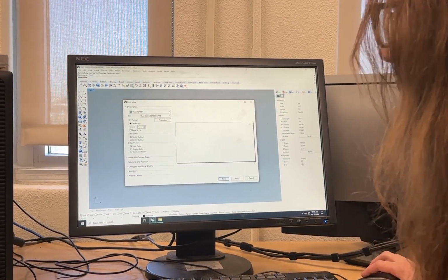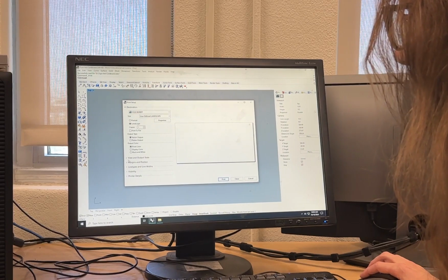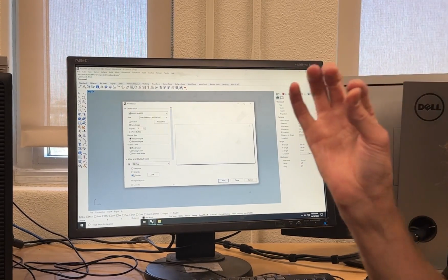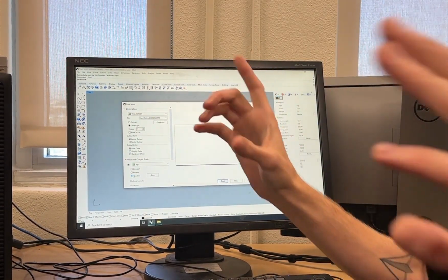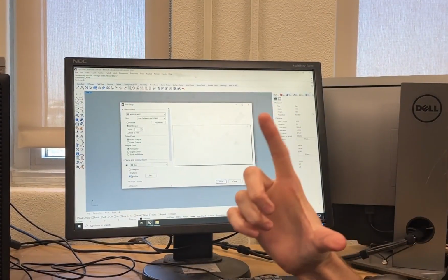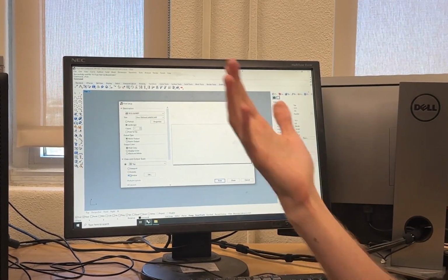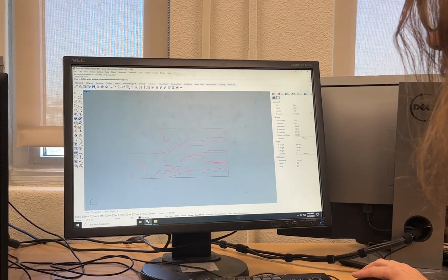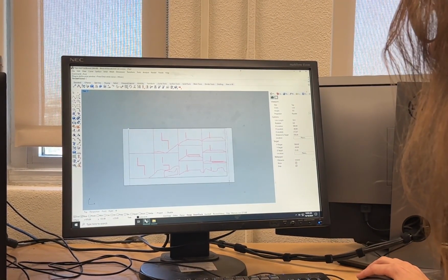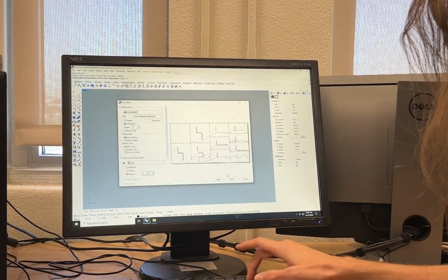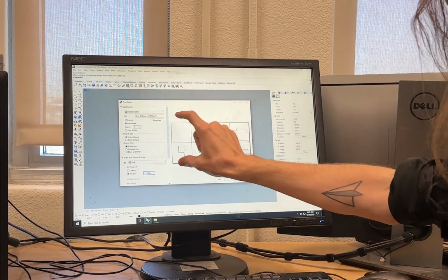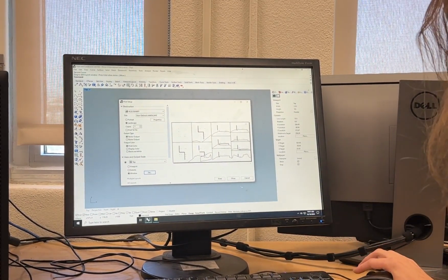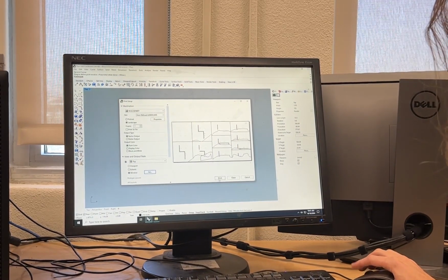Lastly, we need to go to the view and output scale, and we need to select window, right? Because we made a window for ourselves, and now we need to set that window to this window. And since we set it to scale 12 by 24, we'll have no issue, right? So we'll select window set, we'll click the boundary of the box, enter, voila. And of course you should see it fill the entire extent of the drawing, right? And we're good, press print.